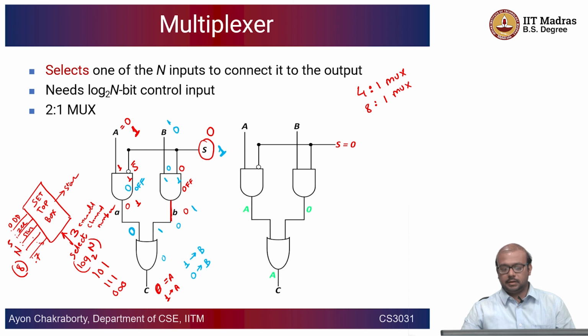So, it is a way you can select some lines and give an output. Okay. This also has a lot of functionalities, right. You want to channelize certain inputs, right. So, you do not want to input everything to a system, right. So, suppose you have some mechanism for selecting some inputs. Okay. So, let us say the first input and the fifth input has to be chosen and added. So, those kind of things can be controlled by the select lines of the multiplexer.